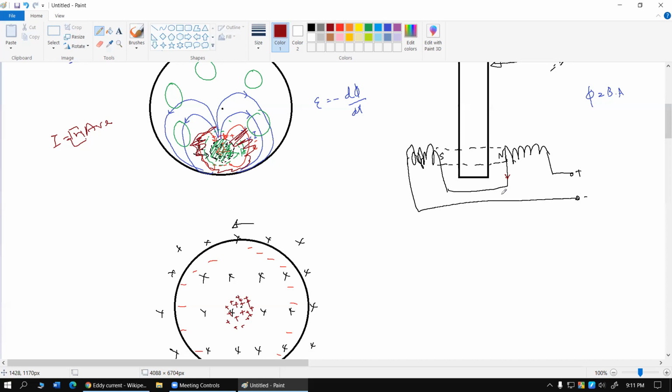As the vehicle slows down, so the rotation slows down, you can, I'm not going to say proportionally, I'm going to say compensatively, if that's the word. You can increase the current value so that whatever you are losing because of the speed, you can compensate for it with a higher current from your coil. So you can maintain uniform deceleration, which is very important for the comfort of the passengers.